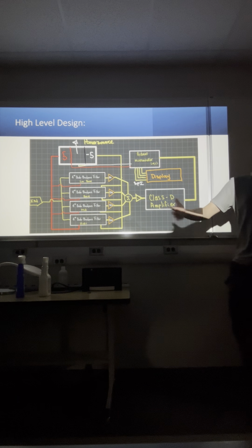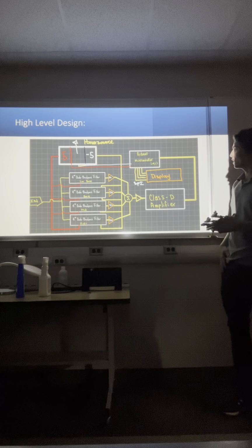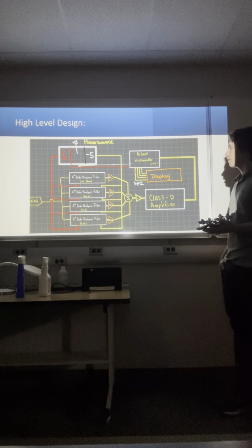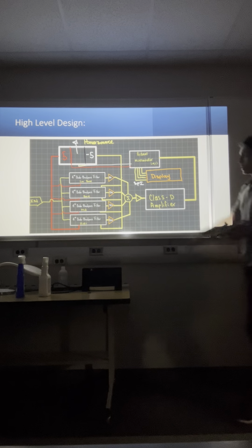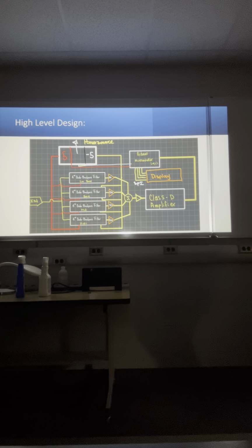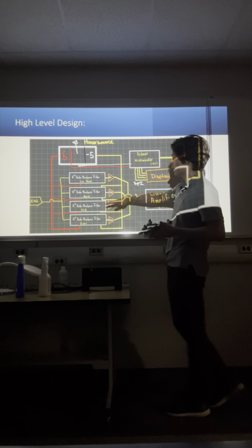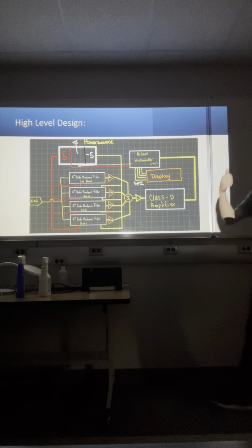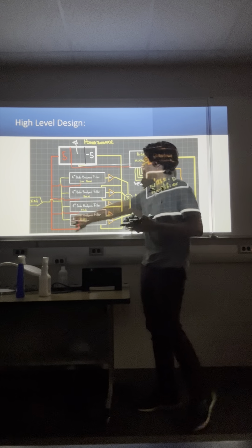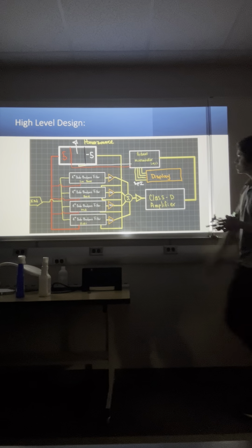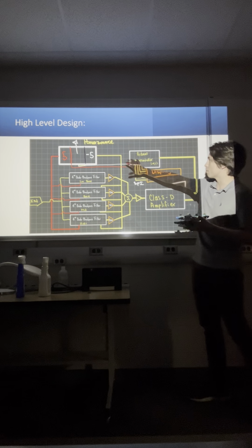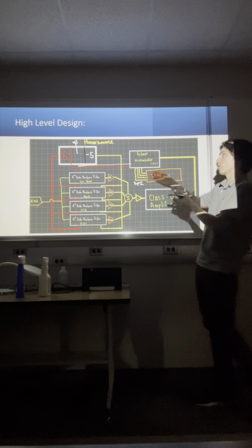So I guess when we first did our first presentation, we had a bunch of stretch goals. Turns out we weren't able to do any of them other than the PCBs, which were a very interesting thing to learn. So right here we have 4 stages of 4th order multiple feedback bandpass filters, as we first discussed in the first presentation, with each stage having an inverting amplifier at the end to apply a boost or cut to each stage, as well as embedded within the actual block, a buffer in the beginning, which we'll touch on a little bit later. That goes into a summing amplifier, which then goes into the Class D. And then all of these are sampled by the Arduino microcontroller, and then we have our spectrogram on the display.